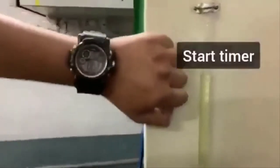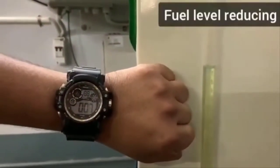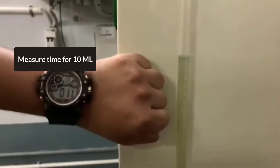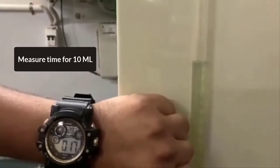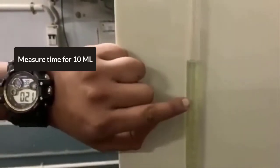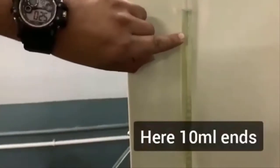After opening the valve, we will start our stopwatch and keep it on until 10 ml is consumed. So for 10 ml we will measure the time, and for that we need a stopwatch. Here you can see the stopwatch is working, and the level is coming down. That means the diesel is consumed in the engine.